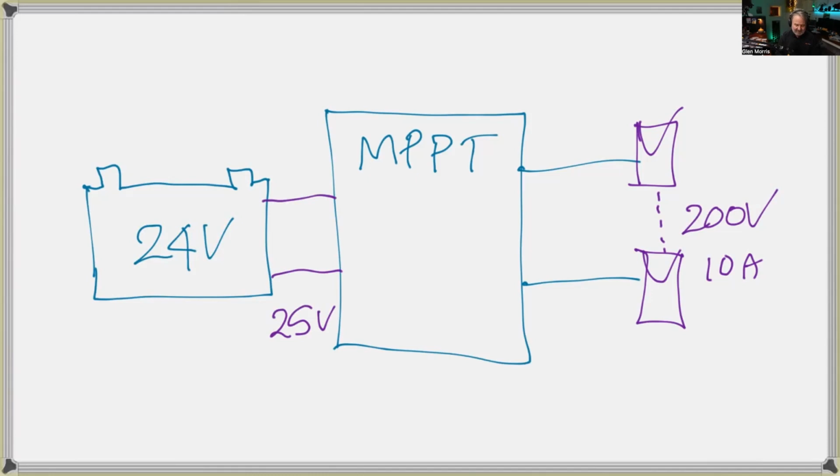It's not very hard. So 2 kilowatts of input power divided by 25 volts tells me that we've got, the number you just said, 80 amps of current coming out the other side. Yes. So in MPPT, Australian invention, converts voltage and current to match what the battery system needs. It does one other thing, and this is actually even more important, and it applies equally to solar inverters and dedicated charge controllers, is it controls how the array works.